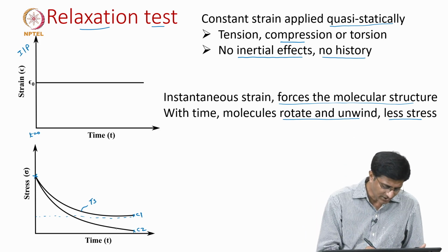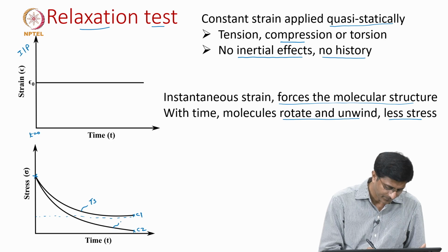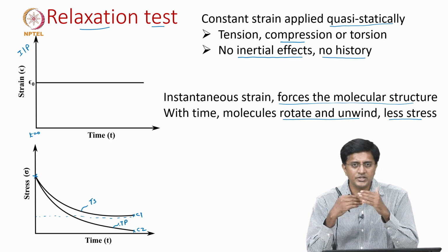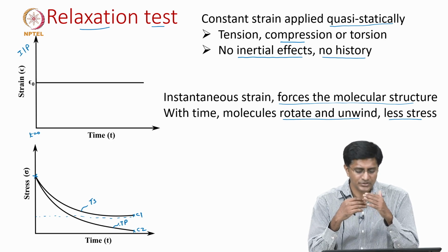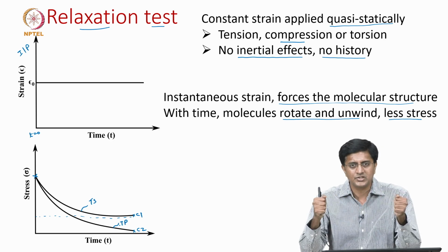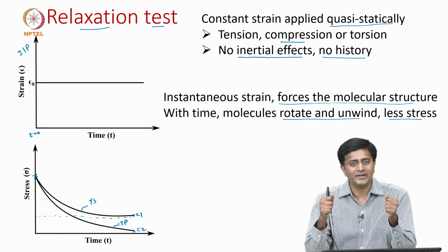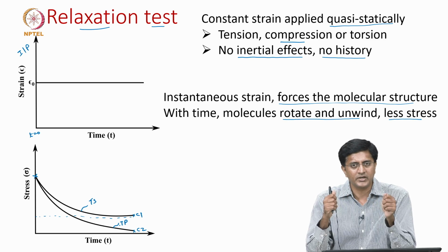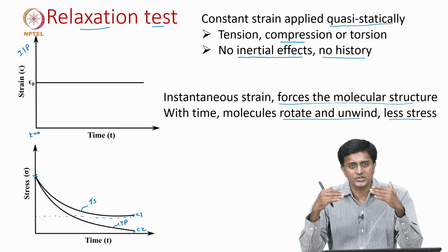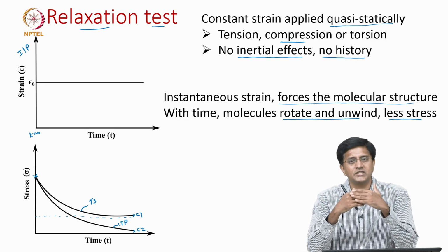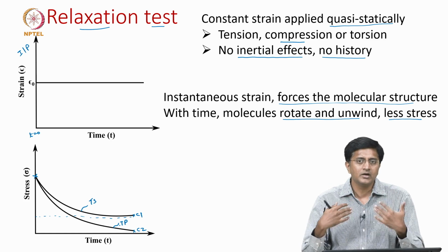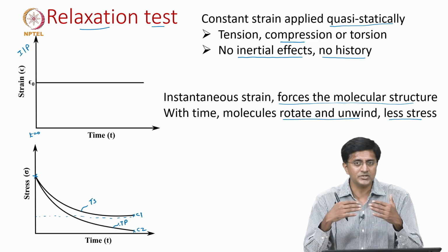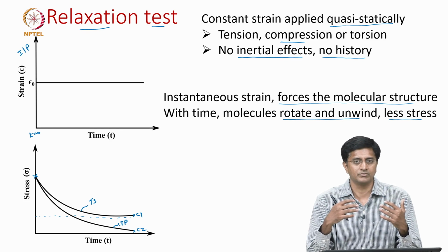But for thermoplastics it is slightly different. In thermoplastics, as we know, the molecular chains are bonded by secondary bonds. Once we stretch it, there is a stretch happening in the molecular chains between entanglements, but given enough time these molecular chains can slide past each other and reduce the stresses. If we give enough time, it flows.